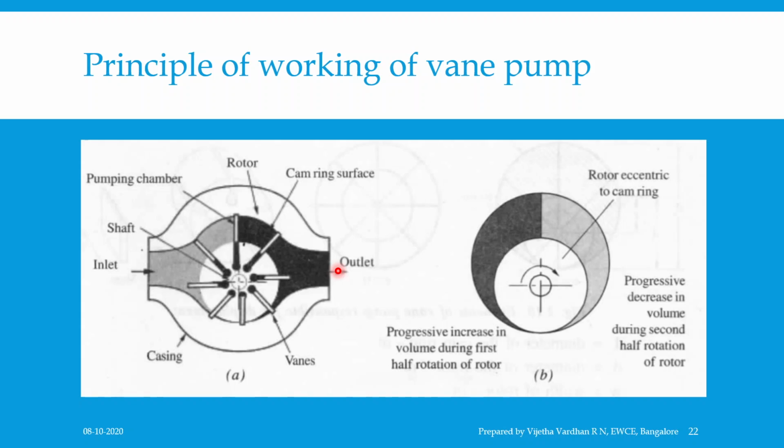The pumping cycle occurs twice in each revolution in the case of a two-vane-per-slot design, and the displacement of the pump depends on the width of the ring, vane, or rotor and the distance the vanes are allowed to extend from the rotor surface to the ring surface. The contact between the ring surface and the vane tips results in wear of both the ring and the vane tip.